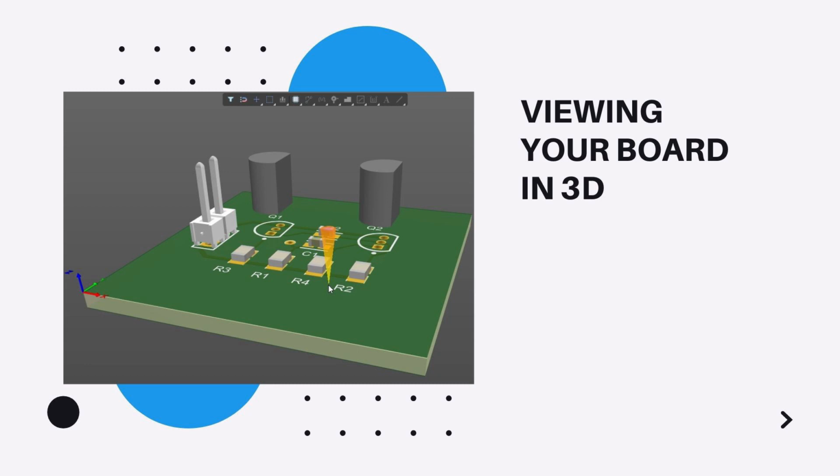3D layers have a transparency setting. Slide this to see through the objects on that layer. You can choose to show 3D bodies or hide them. To display the components in 3D, each component needs to have a suitable 3D model, included in its footprint. Refer to the Component object page and the 3D Body object page to learn more about including 3D models, and refer to the 3D Advantage in ECAD-MCAD Integration page to learn techniques for positioning a model on its footprint.